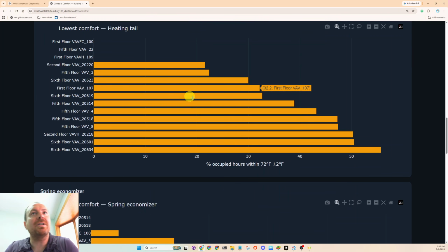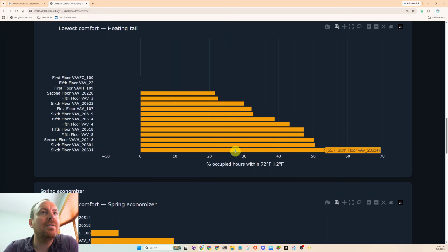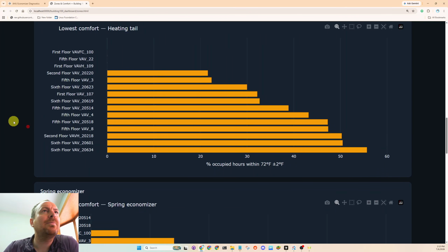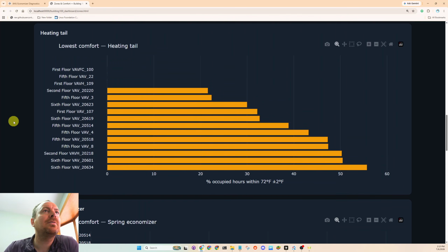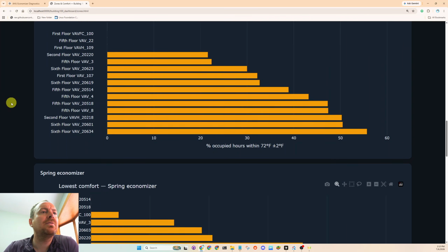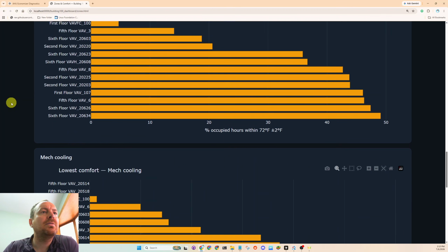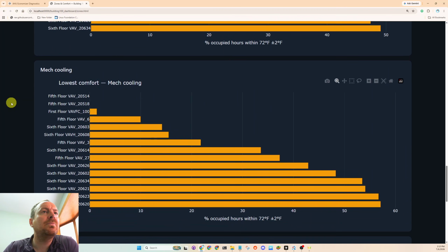So we do have some, like, the lowest ranking VAV box. Lowest comfort. Percentage of occupied hours within 72 degrees with a 2-degree tolerance. So apparently these guys are the worst. Good to know.